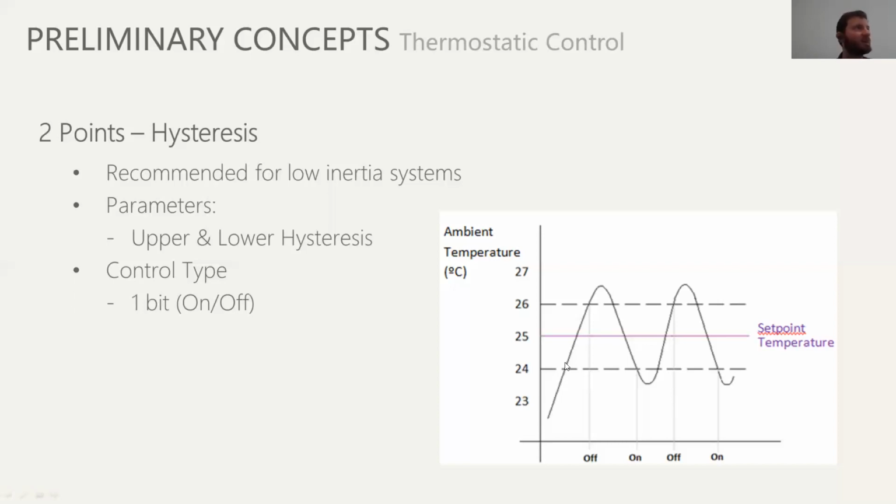I'll just try to draw that somehow. Yeah, so we are starting heating the room. That would be that, heating the room. We go through our lower hysteresis and we don't turn off the system. It still goes on because it's low inertia. And when we reach the upper hysteresis point, you can see the system turns off.